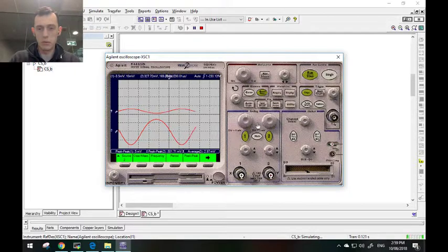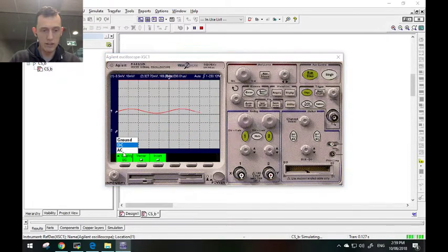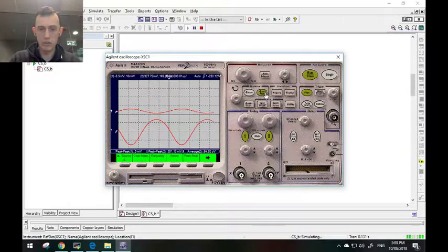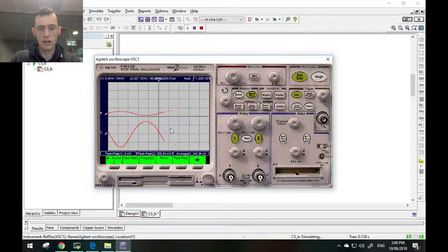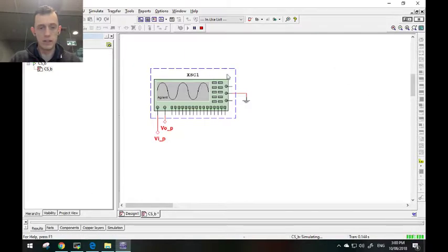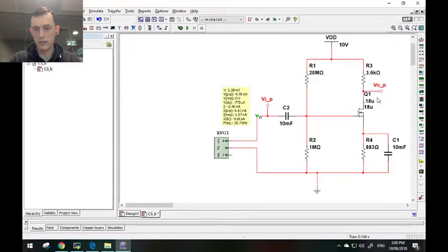That would probably explain why the system wasn't going well. Let's just change this from DC to AC. Potentially there was an issue there. So let's see, quick measure. One thing that we do know is that it's not possible for this one to be oscillating around 0 volts, but that's fine. We'll go and check this. Looks like it's okay.